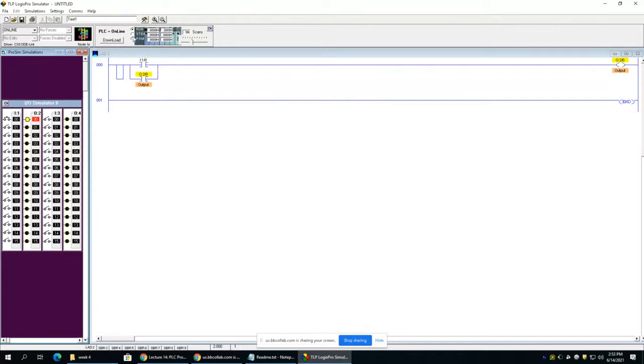So I'm going to right-click on it. Let me go back to program. I'm going to right-click on this, and I want to use this physically has to be a normally closed button. That's my stop. And so when I come in here to actually use this, here's where you can get confused if you're not careful. I can drag this over here, and I can actually put the stop button anywhere. I can put it right there if I want. I can put the stop there, and I'm going to map it to there.